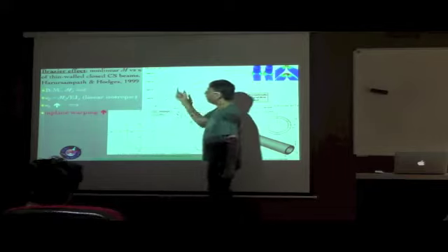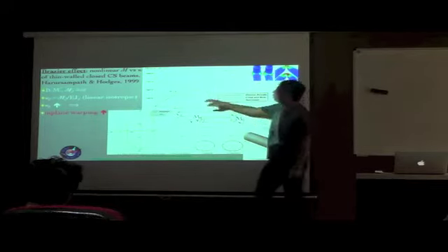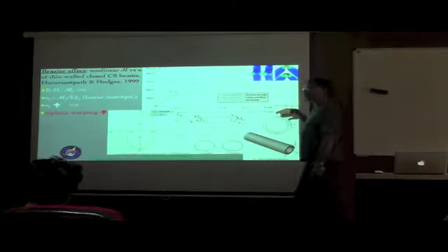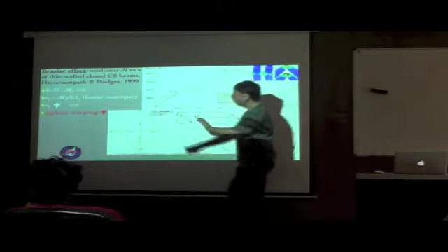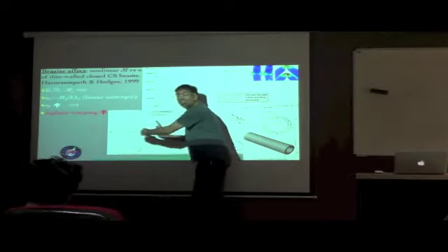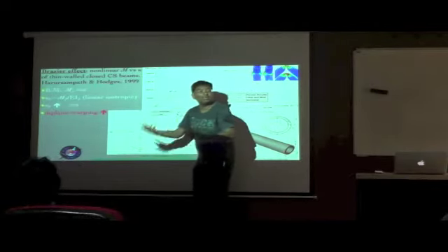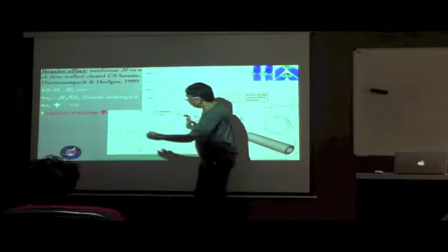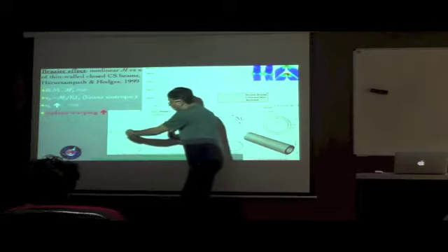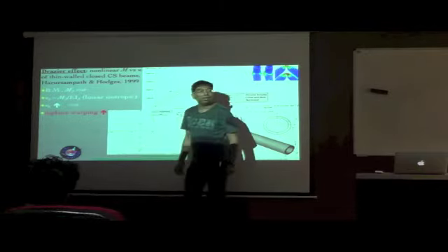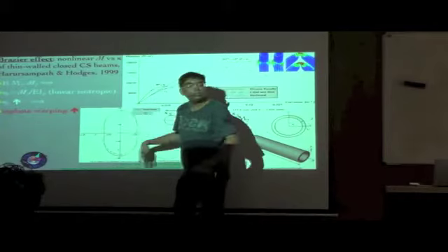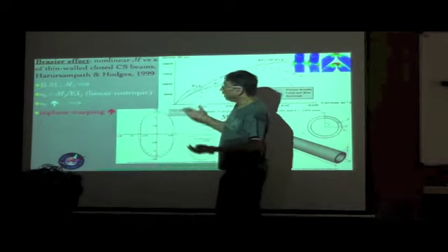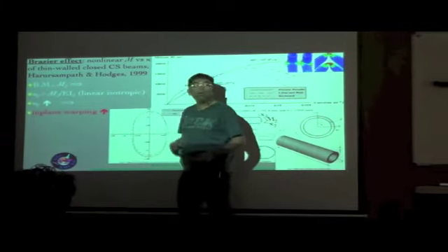And again, the asymptotically correct result will not only give you the bending moment versus the curvature relationship, it will also tell you the actual geometrical change which is happening on the cross section, because that is the warping, and you have closed form analytical solutions for the warping as well. So depending upon the value of the bending moment, you can actually plot the new shape of the cross section, which is non-circular, of course.